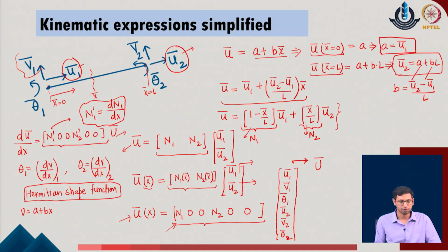So, I can describe it by the function a plus bx plus cx square plus dx cube in the given problem. Now, while describing the boundary conditions or the nodal values of the given system, I must define that v bar at the position of x bar equal to 0 is equal to v1. This is the first condition.